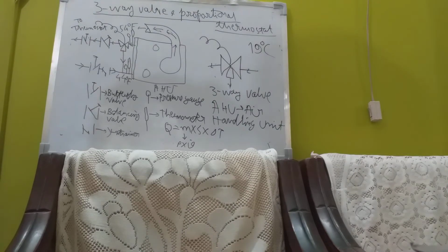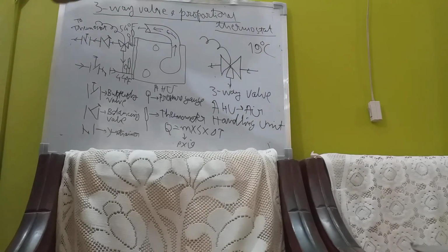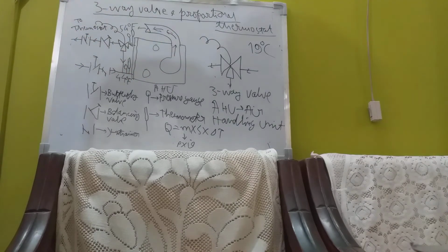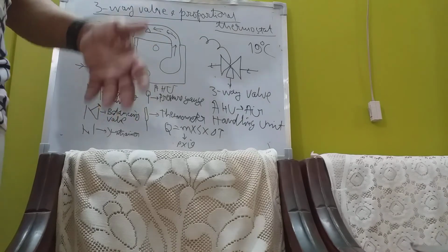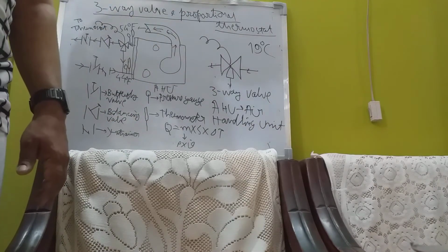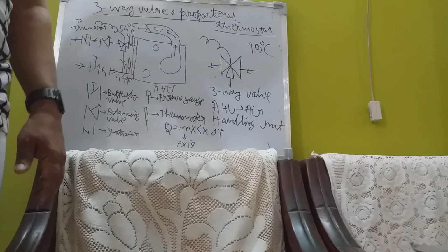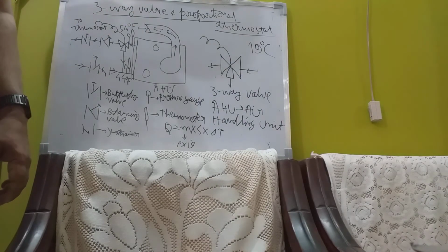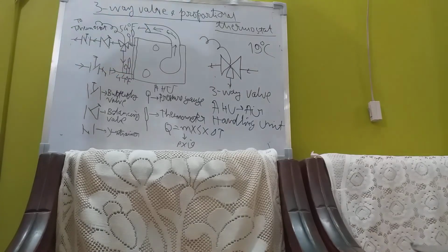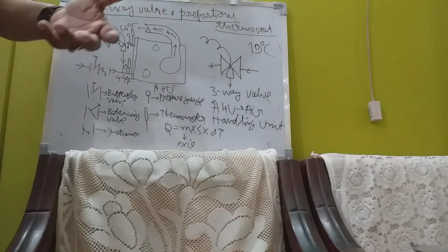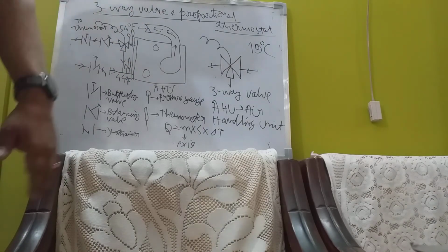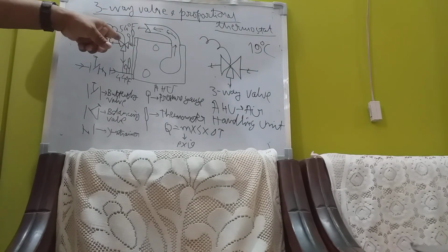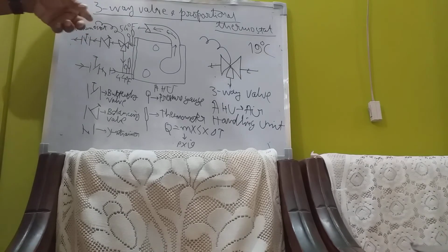Like in case of classroom buildings in educational institutions. Some classes are happening, some classes are not there. In that case, you need not run the whole system for classrooms. You have an FCU, you close down the FCU and go out of the class. There will be no electric bill for that, and there will be no chilled water circulation for that. So, in case of FCUs, instead of the proportional thermostat, an on-off thermostat is provided.